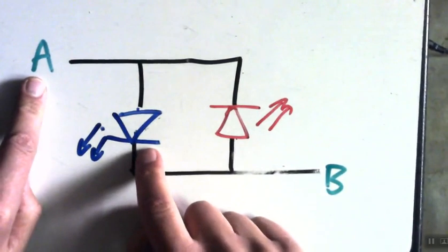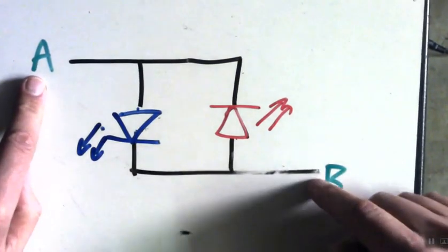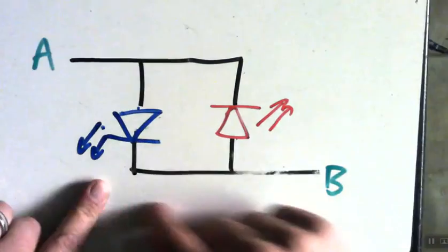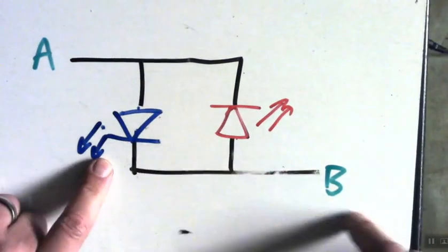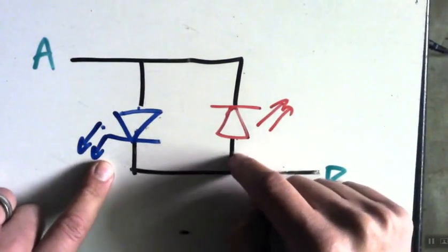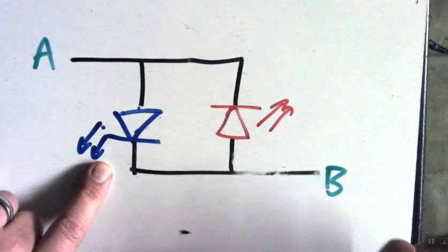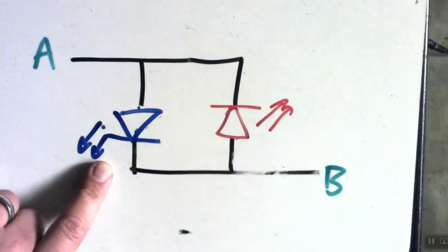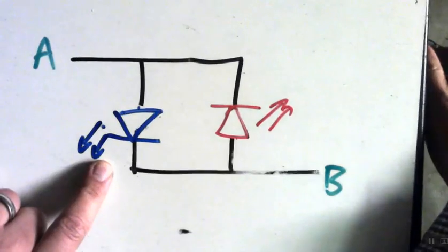Let's make it a green LED so the thing is on. When the current flows from B to A, it can't flow through the blue one, but flows through the red one, and we'll have a red light shining. So that is typically like some charger devices.